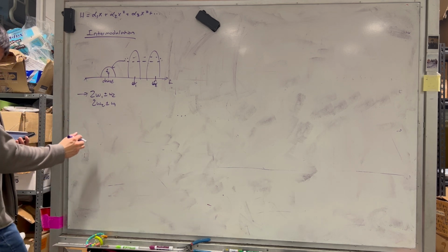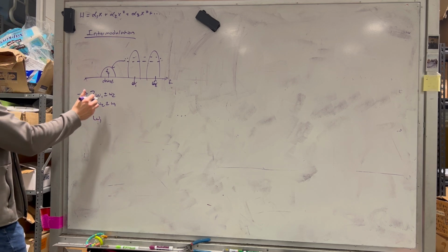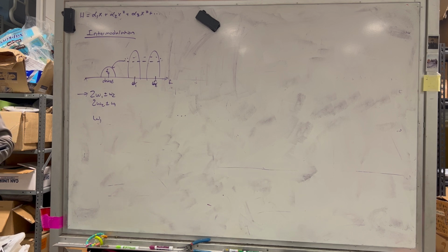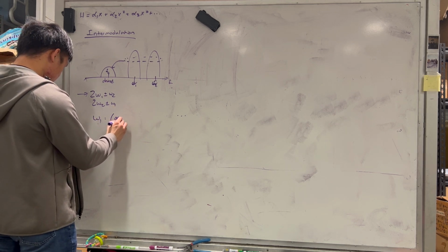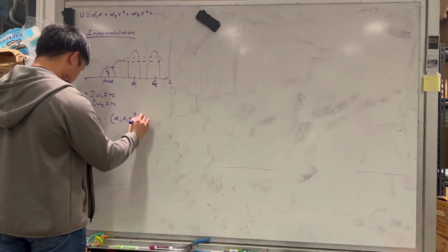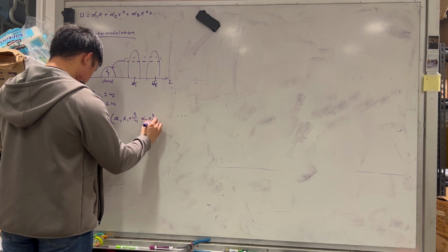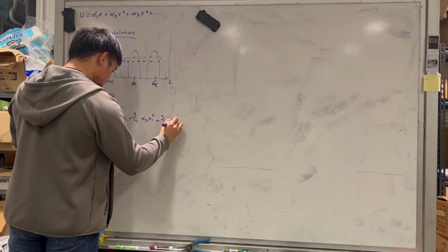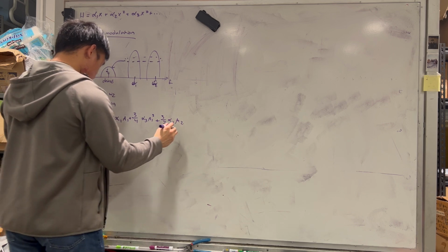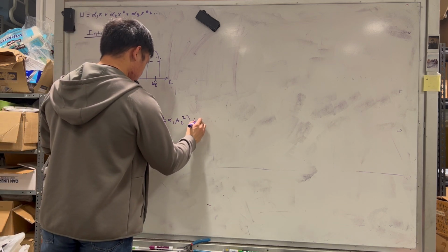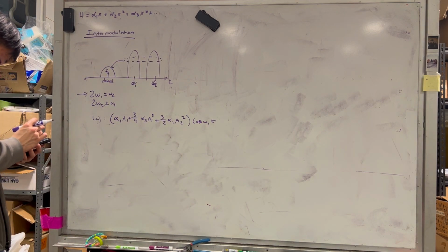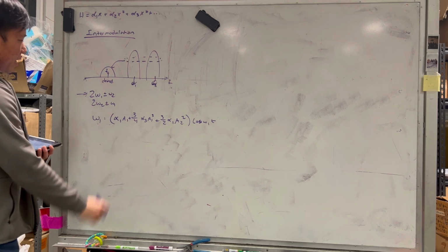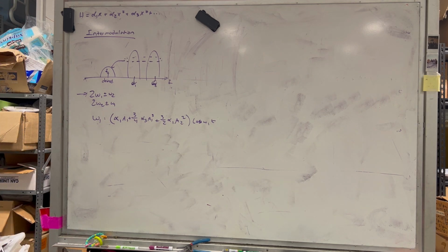So essentially, when you write out the terms and you throw x equals a1 cosine omega 1 t plus a2 cosine omega 2 t into that system, at omega 1 you see alpha 1 a1 plus 3/4 alpha 3 a1 cubed plus 3/2 alpha 3 a1 a2 squared, at cosine omega 1 t, and then you get a kind of similar thing for omega 2. I don't want to write it down.